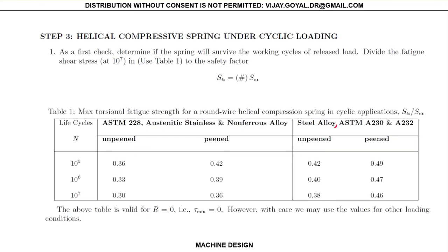We will talk about the fatigue of helical compressive springs. To start this discussion, the first thing you always have to do is your static analysis. You cannot start any analysis, not even the spring or any substructure, without it. You always do your static first, and then you check for cyclic loading.